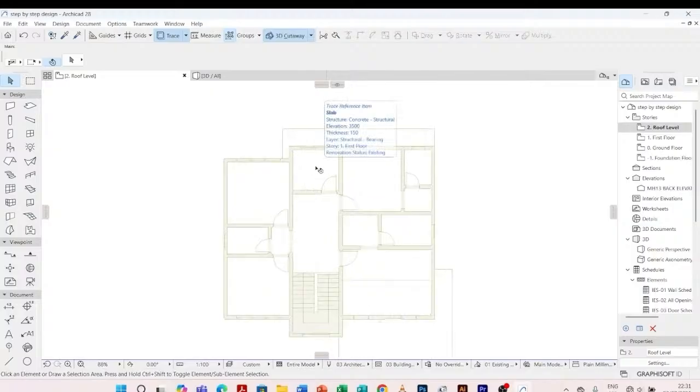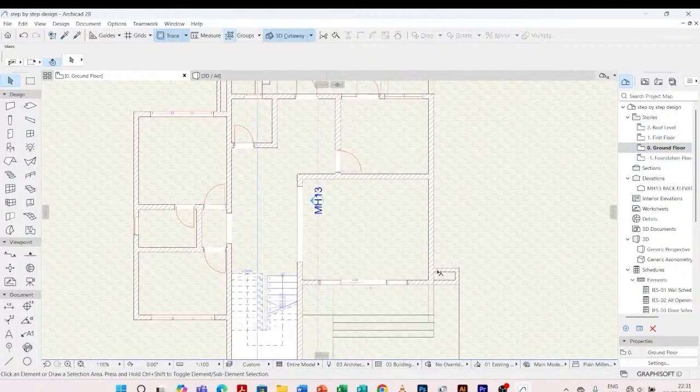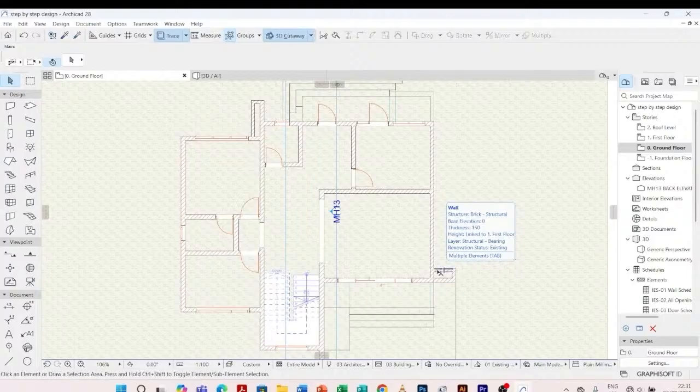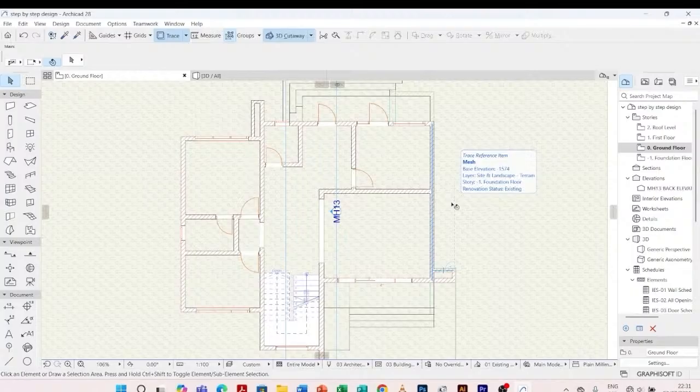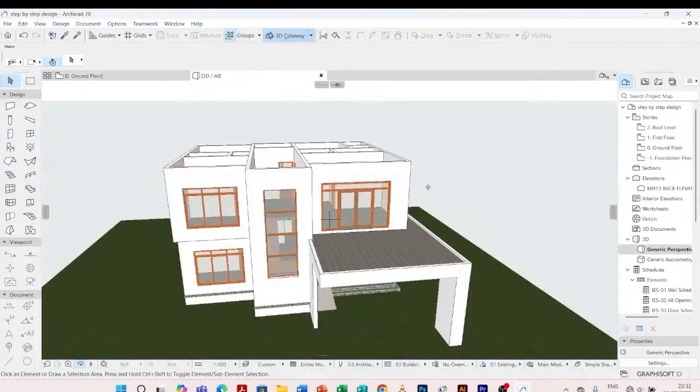So we are going to have our slab partitioned in two ways. Actually, let us first see where our ducts are. That means these ducts I've created, I'll have to make sure they go up to the roof so that they collect water from the roof. So that means I'll have to move them up.